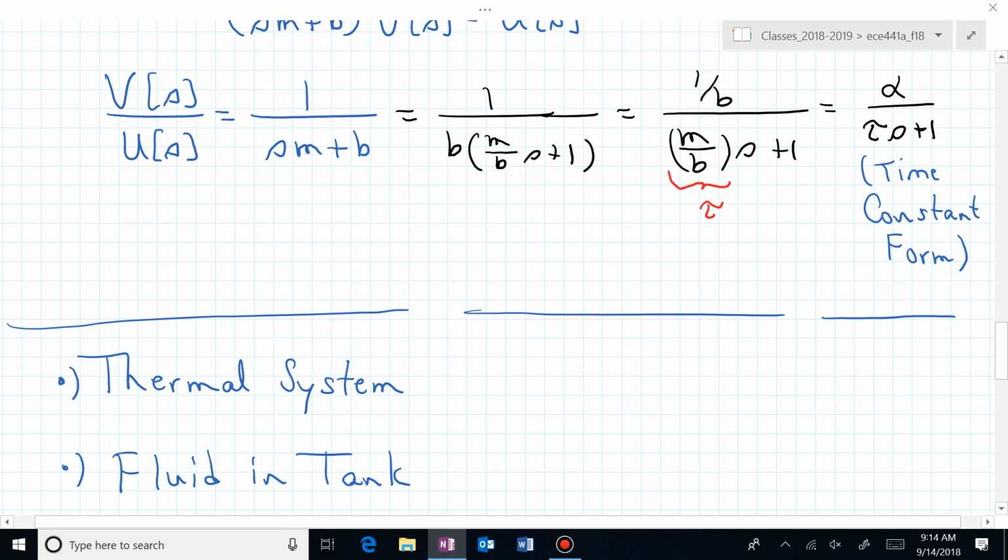If you kind of back that out, you'll find that that translates into us just glowing like a 100-watt bulb all the time. So now if you wondered why did the room heat up when we put 100 live bodies in it, that's the reason. That's why it takes some conditioning to maybe stabilize that temperature in the room.